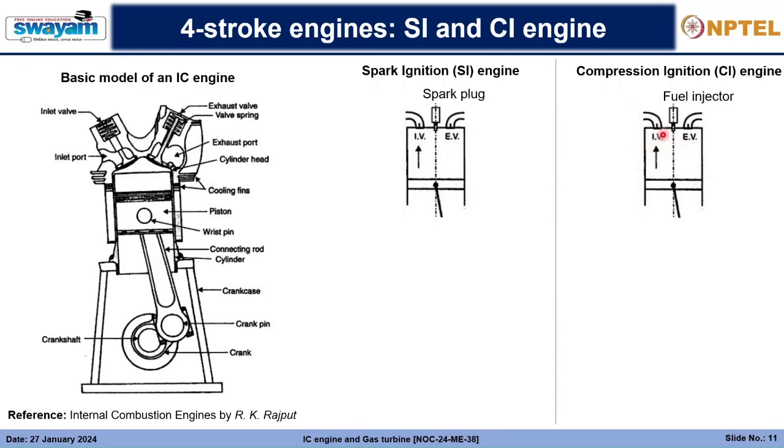The oxygen is needed to ignite, and due to the high pressure and temperature, it will quickly ignite and catch fire, and accordingly the volume will tend to increase. But not letting the volume increase will increase the pressure, and accordingly we will have a force acting on this piston. So that's the case between compression ignition and spark ignition.